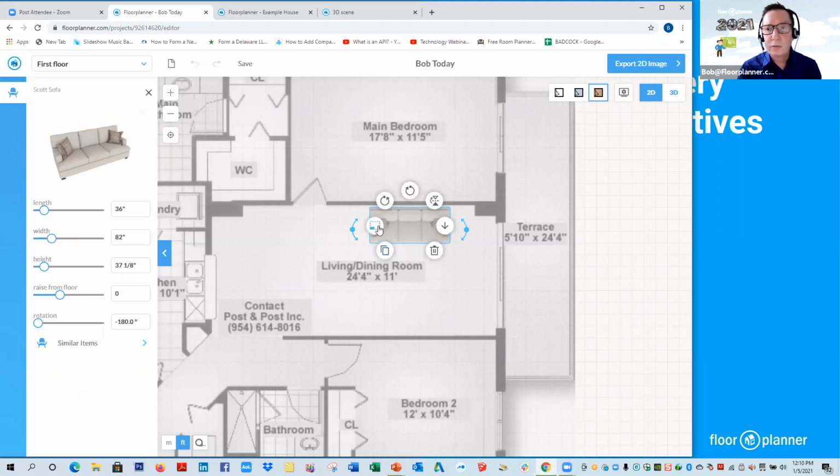Or I could scale it freely, although I prefer to scale it in the editor window because I know the exact dimensions. You can rotate it in both directions, 90 degrees. You can flip it, although flipping it is left and right, not front and back. You can press down. Press down means it's trying to get on the surface that's directly below it. Right now it's sitting on the ground level, which is 0, so it's fine.